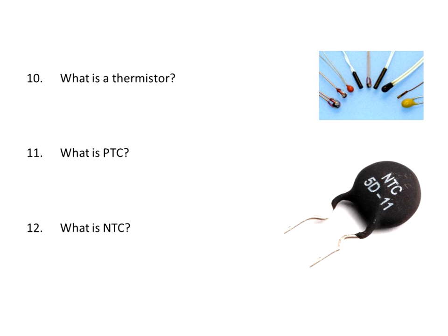That's what it is. Now there's two kinds of thermistors. A PTC, which stands for positive temperature coefficient. And the way that you want to think about the reaction of a PTC is, when the temperature goes up, the ohms or resistance goes up. So in a positive temperature coefficient, the resistance will increase with heat. That's how you want to think about it when you're talking about the reaction of a thermistor, if it's a PTC or if it's an NTC.